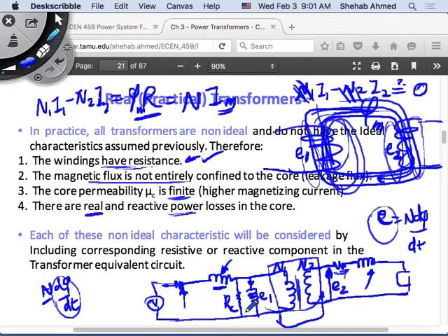Okay? I need it. It's not a voltage drop in the path that will reduce the amount of flux flowing in my core. It's not. It's something that I actually need to create this mutual flux. I have to have it there. So I will represent it as something that will always exist with my voltage. Anytime I generate the voltage on a winding that is caused by the linking of the flux of both windings, then I will have this loss. It will always exist.